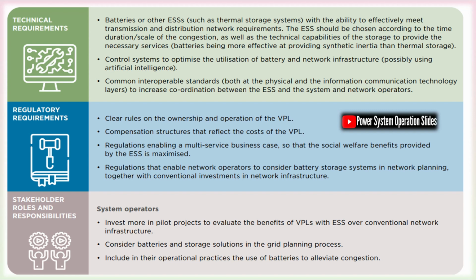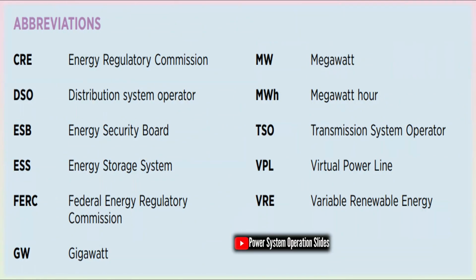A utility places a battery at a grid boundary and uses it during peak export hours to relieve a congested corridor, coordinated by EMS. FACTS deployment with optimized OPF: installing a STATCOM or SSSC and running real-time OPF to reroute flows around a constrained element. DLR plus topology switching: using DLR together with switching schemes and redispatch to allow temporarily higher transfers during favorable weather. DER aggregation: an aggregator coordinates rooftop solar curtailment and flexible loads as a virtual tie to relieve inter-area stress.